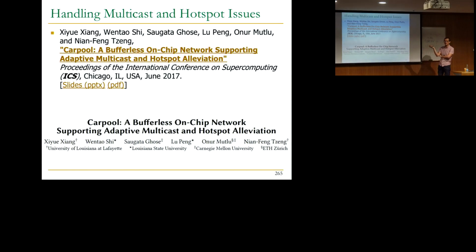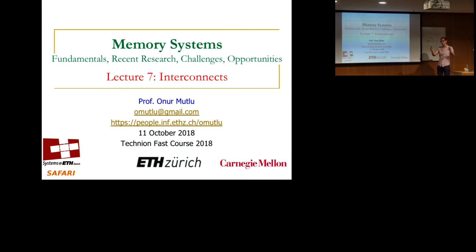The whole push for MECS, for example, was to reduce latency. Mesh is terrible in terms of latency. You go from router to router to router to router. So that's why you actually need low diameter. That gets you to your memory much faster also. If you have a diameter of 1, you're directly at the memory controller, right? Of course, you pay the interconnect latency somehow. I don't know if that answers your question, but you need to design your interconnect nicely such that it's low latency. The MECS approach or the Kilo-NOC approach is really trying to get low latencies. And the SlimNoC approach that I didn't talk about is also to get low latencies, so that you can communicate from point A to point B very quickly without a lot of overhead. So latency is still important, no question about that.